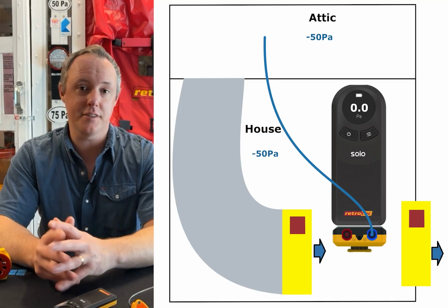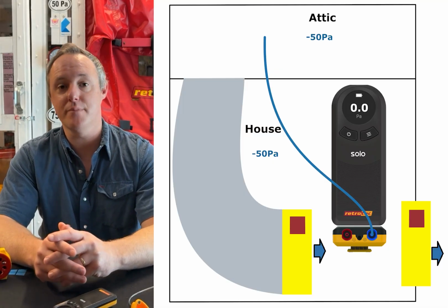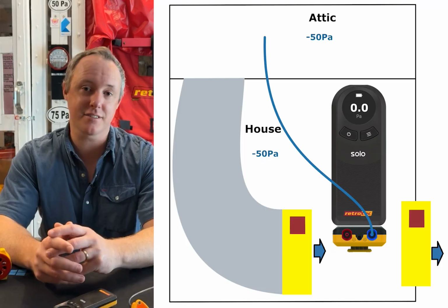And I need to add too, if we're talking about a very large house that might have a lot of leakage through that spray foamed attic assembly, and a duct tester is not going to be enough, you can actually use an additional blower door fan too. We make a kit just for this. It's actually used in a totally different industry, but it's the perfect fix for this.